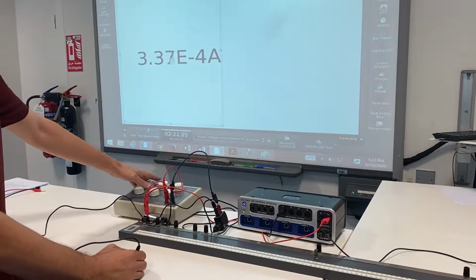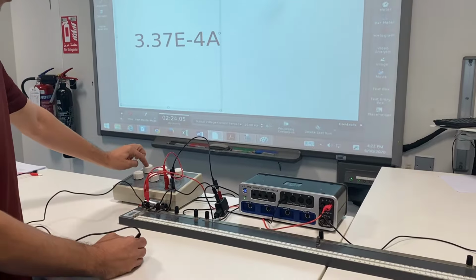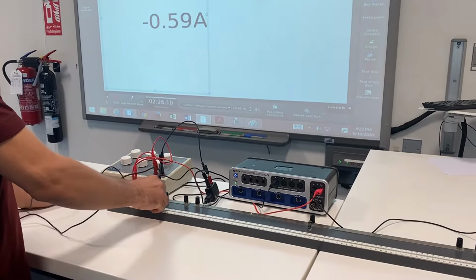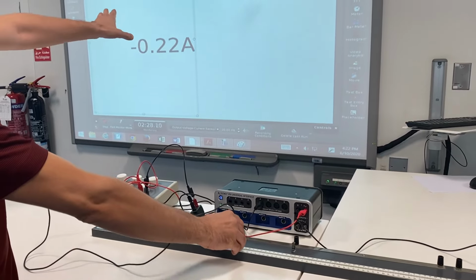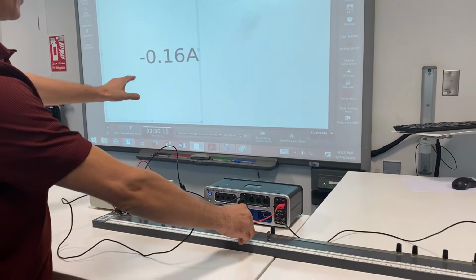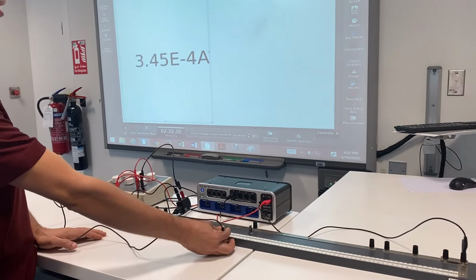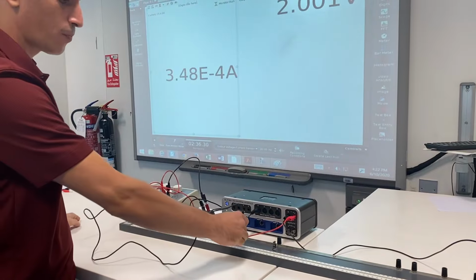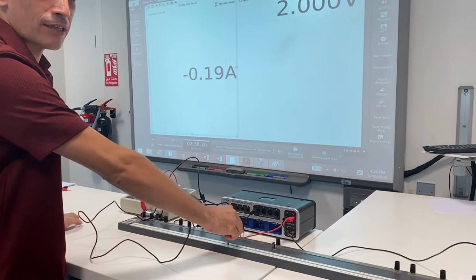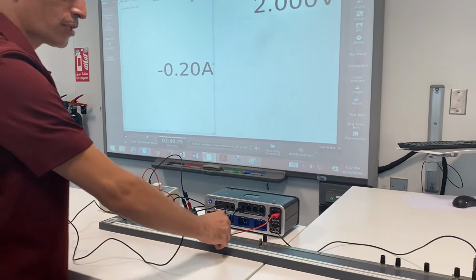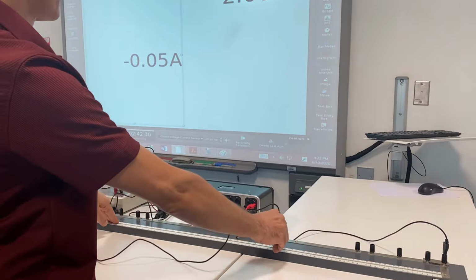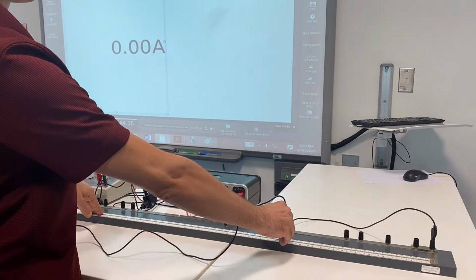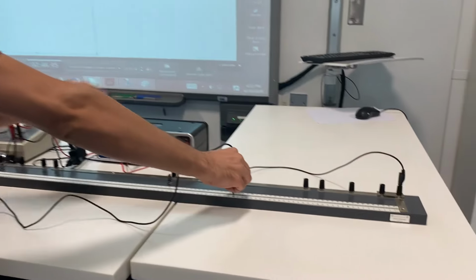Okay. So here we have the resistance box set to 5 ohms. So I'm going to scan quickly while watching the screen there. Now notice if the pointer slides off the wire, I also get something very close to 0. So you have to pay attention to this. You have to make sure that the pointer is actually touching the wire and you're having a 0 at the same time. Here is the first reading.